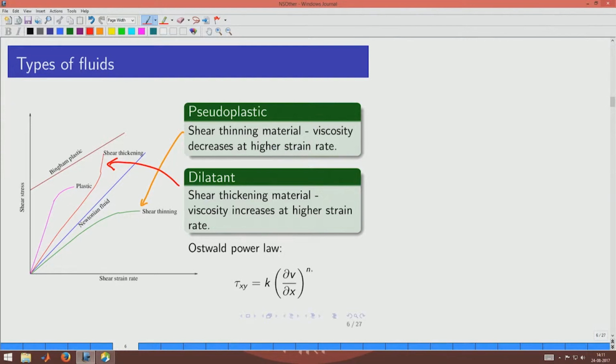You could see that you can no longer use the linear law and need to use a power law, and here is a term that makes this type of fluid different from the Newtonian fluid, which means that these fluids at low strain rate could perhaps be modeled as Newtonian, but at high strain rates you need to modify it and the power law will come in.